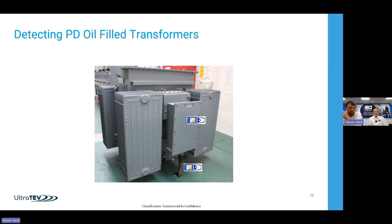Additionally, for the air-filled cable boxes, we want to try and get an air path in there to see if there's any termination activity, any surface activity. Quite often these are vents on the base up around by the bottom of the cable, where you can get a clear air path in. Or in the case of a sealed box, we look to use our contact probe, which allows us to pick up the ultrasonic activity, so that's surface type discharge, through the skin of the metalwork. So not a preferred option, there's obviously an attenuation path in that, but as you'll see in a minute, it does work, and you can see inside that sealed box.